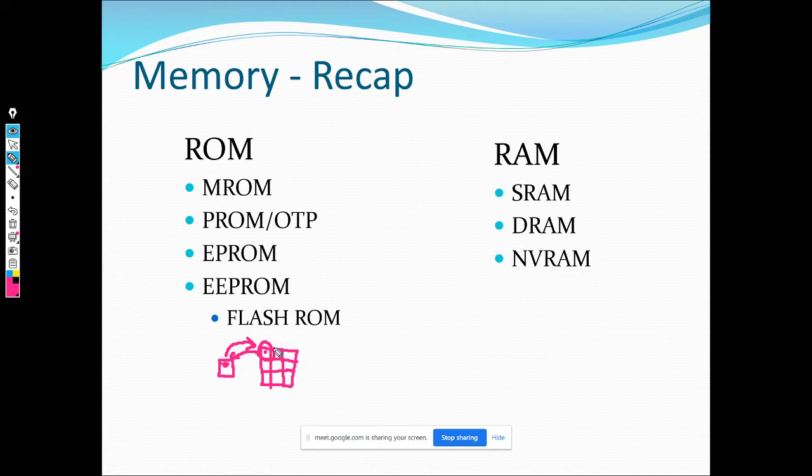So it takes the entire block. Even if only one bit is changed inside this block, you have to take the entire block out, rewrite that bit, and put back the entire block. So you can only erase a block; it's block erasable. That is how flash ROMs work. The good thing is you've separated the other blocks. Previously, if you wanted to write one bit of memory, the entire ROM would have to be programmed, which takes a long time. Dividing it into blocks enabled much better read and write. So even though it is called ROM, read-only memory, flash is read-writable, but the name just stuck.